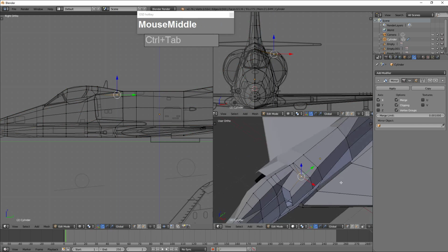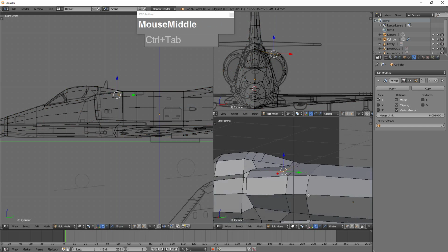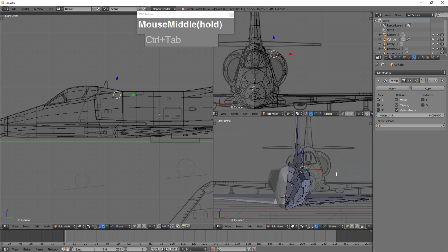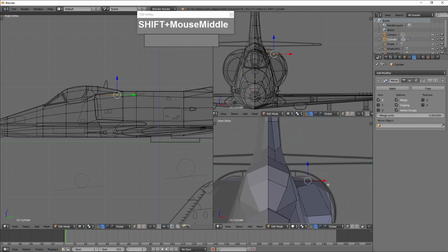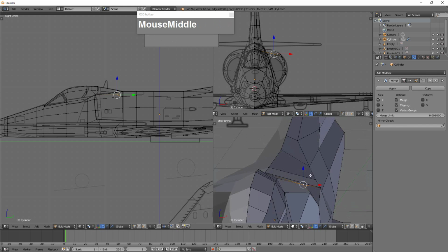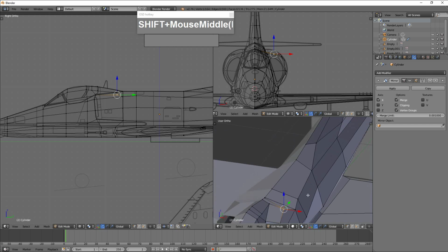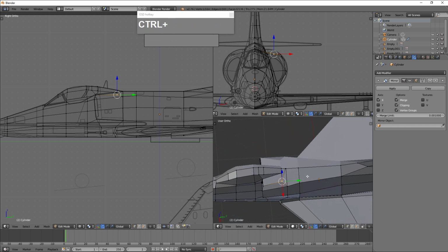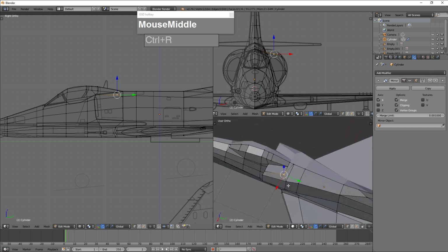So right now I have my jet intake, so you will need some time to move and sculpt the vertices to get it to look proper. And right now there's a lot of empty space here. I'm going to try to insert one edge loop that runs across here. Okay, unfortunately it's cutting across my canopy, which is not something I like.